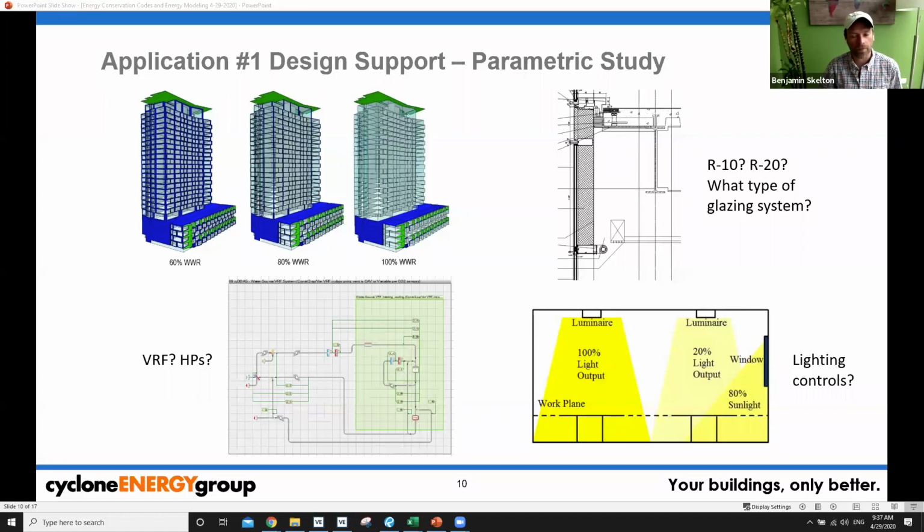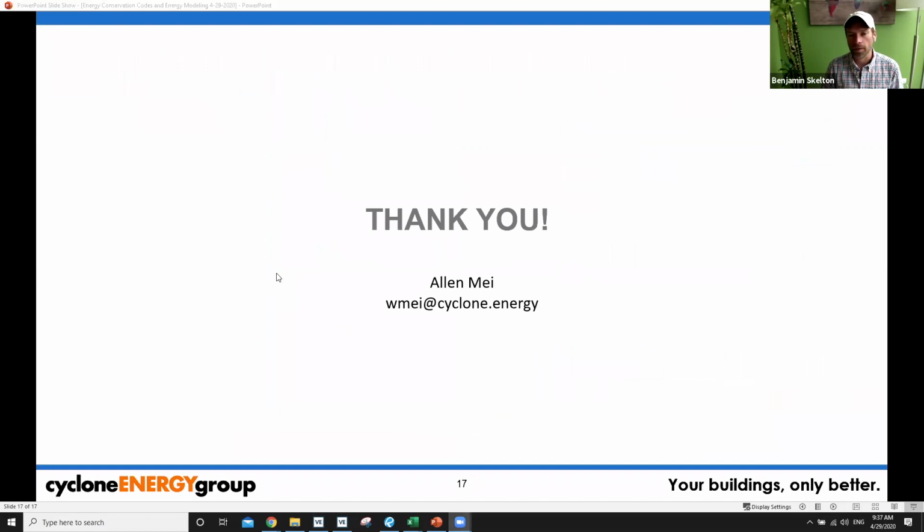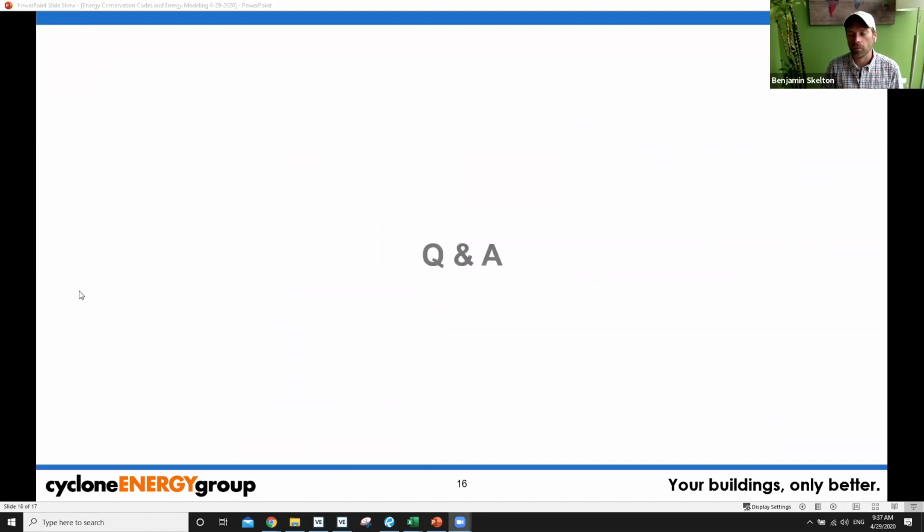I think the closest that we've probably done is some integration with TRNSYS modeling, particularly for geothermal and geoexchange type projects, where we need to look at the soil and see what the thermal drift is that the geoexchange system will be putting into the ground. TRNSYS is very good at modeling things of that nature, where it can do a 5-year analysis of what the drift will be, and we can then identify what the load will be. So we've integrated that into IES before.